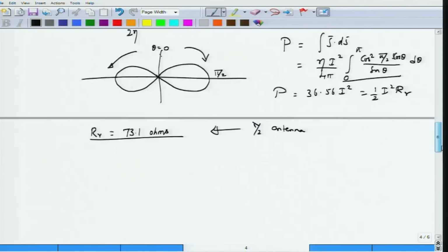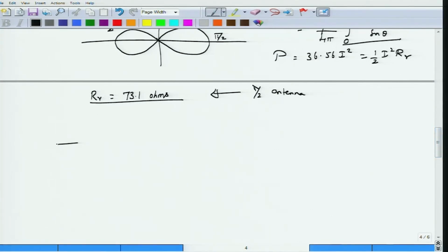There is one curious antenna called the monopole antenna. Okay. In the monopole antenna, you have a ground plane to which you are connecting your signal, and then the antenna itself has a length of lambda by 4. What would be the directional pattern for this antenna? It turns out that because of this antenna, there would essentially be an image antenna of the same length lambda by 4, having the current distribution in this way.